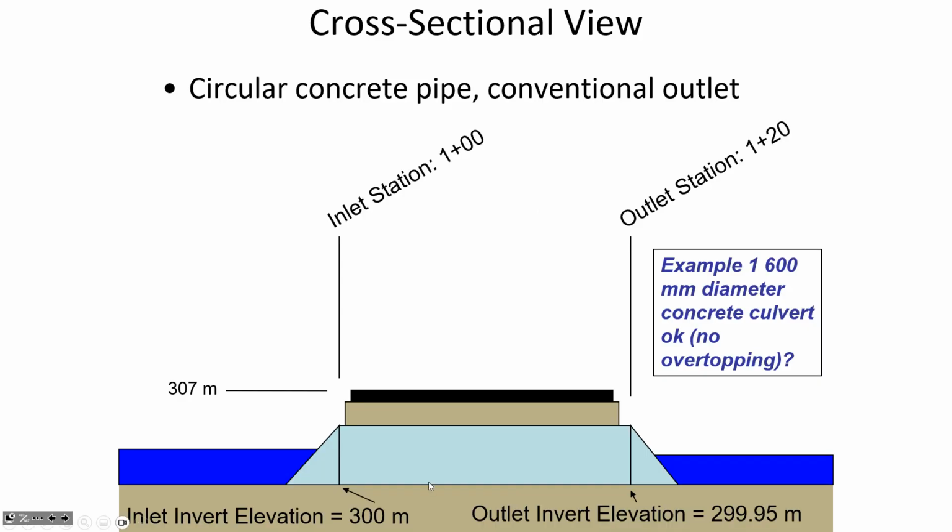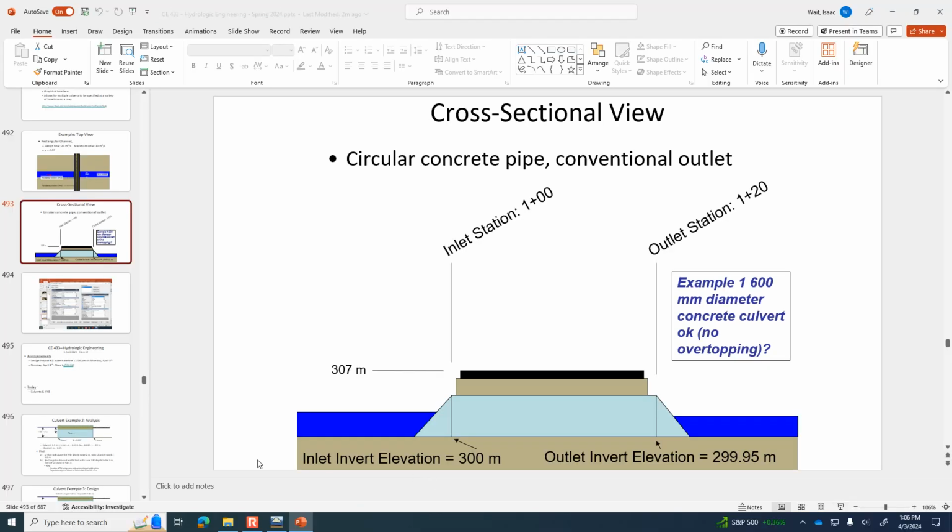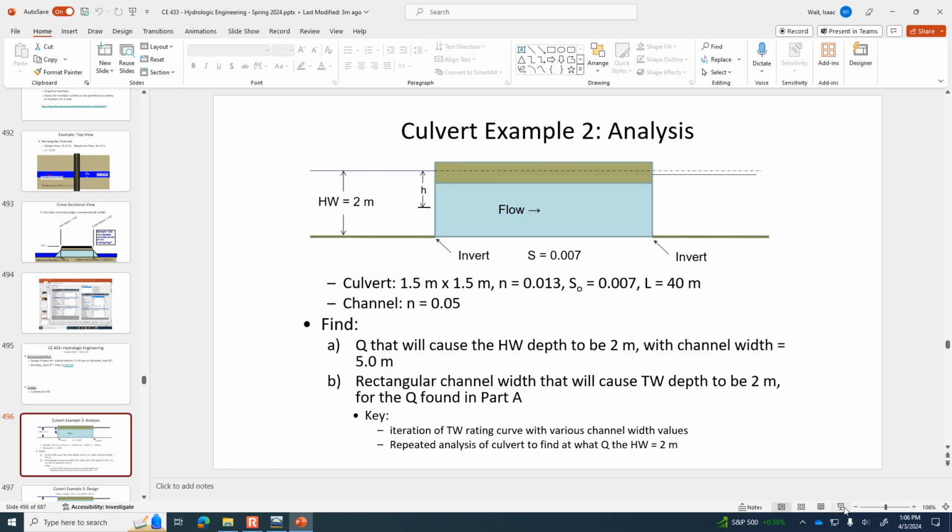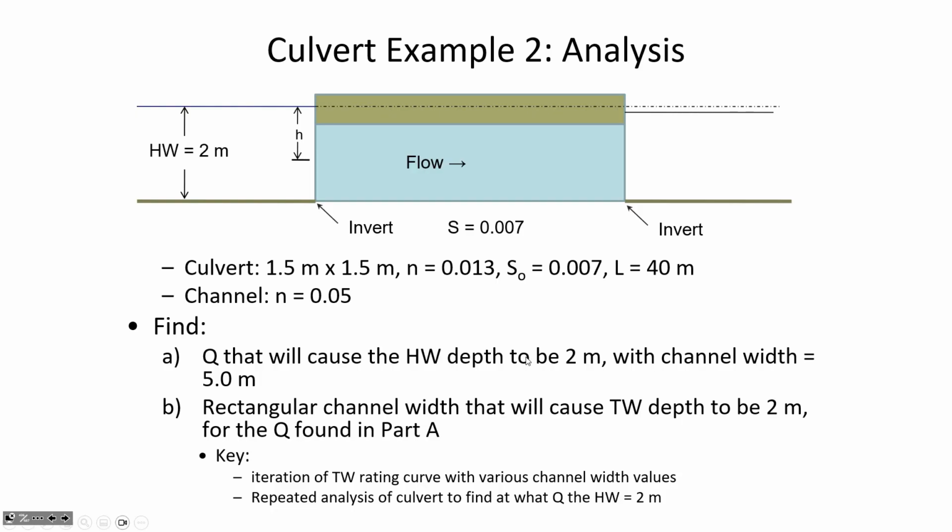And you can determine the channel slope with WMS, for example, it'll tell you the slope of the channel, or you could have known the slope of the channel using elevation data through Google Earth Pro or LiDAR data. But there may be situations where you don't necessarily know the absolute elevation of things, and so you have to basically just assign one.